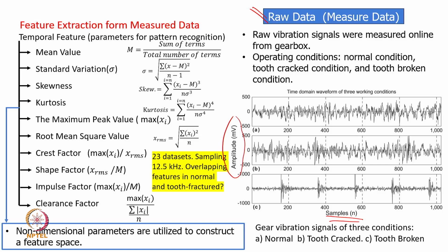Now, you can see in this figure the vibration level is relatively low, while in this case, in some places, vibration is increased. Even look at the vertical axis, it is 0 to 500 and 0 to minus 500, the same. While coming to the broken tooth, they have plotted 0 to 1000 instead of 0 to 500, and 0 to minus 1000. After some period we are getting some peaks, so some sort of characteristic frequency is visible over here.